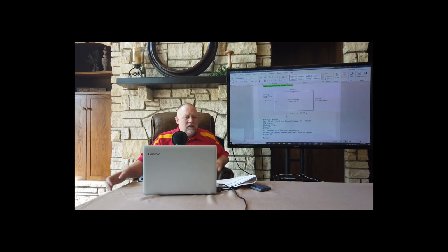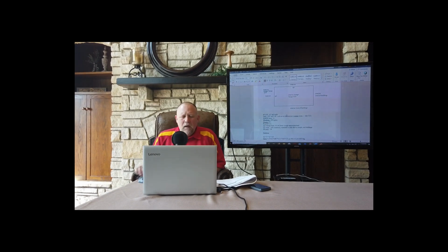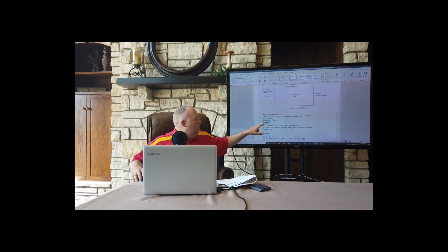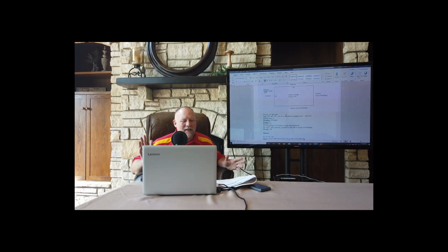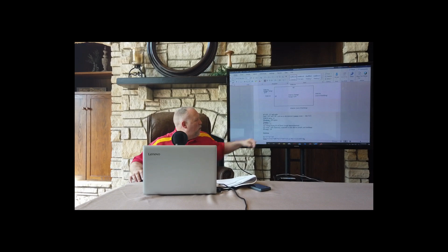Let's assume that those walls are 12 foot high. Like I said, only one of each wall is exterior. Let's give the R value of those exterior walls an R value of 12. Not awesome, but not terrible either. It's not like an old elementary school. Let's give the U value of the glass 0.5, so it's at least double pane glass, and it's okay, not awesome. An R value of 12 is okay, not awesome.